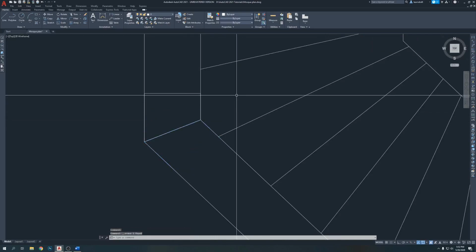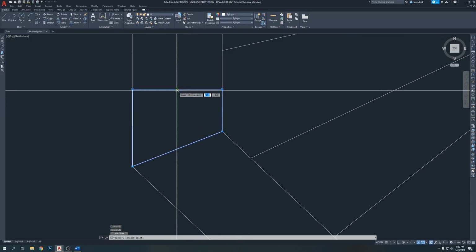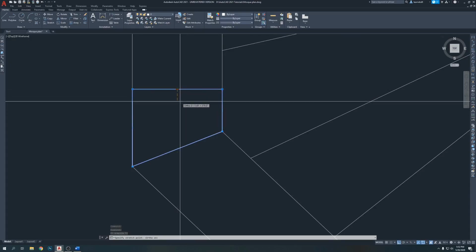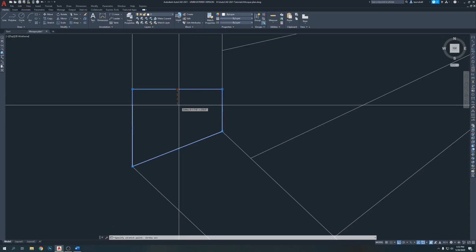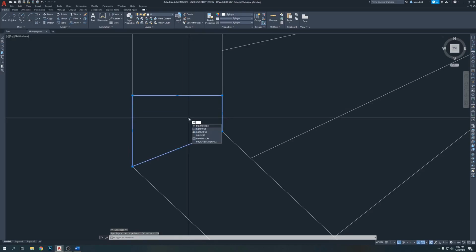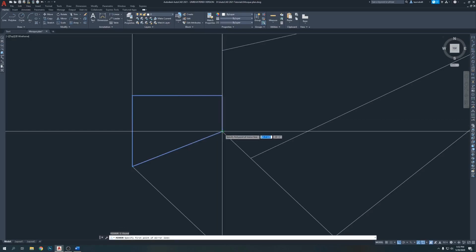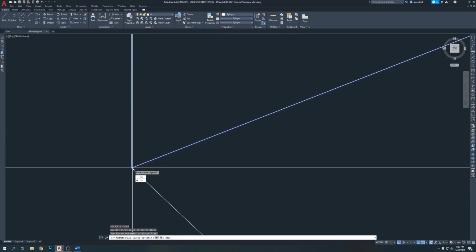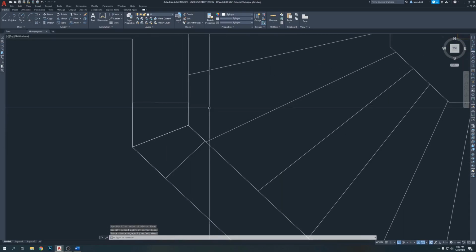But what I'm going to do, I'm just going to bring this one like, okay, F8 is off, so bring it like, if we bring 1 inch, the inside is going to be 7. So let's make it actually 0.75, like 3/4 inch. Mirror, I'm going to need to press F8, enter, click here. Actually you can click there properly and enter, it's going to be there.